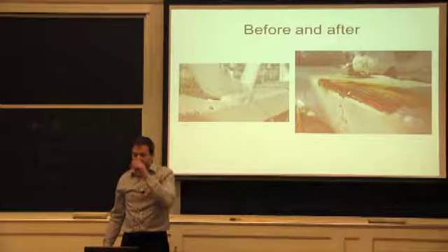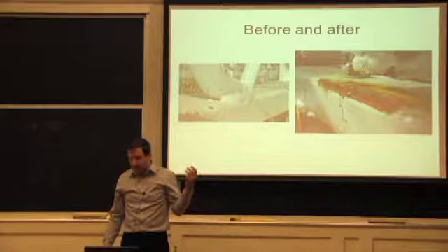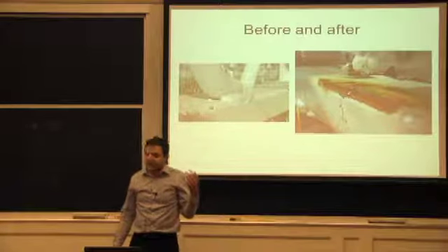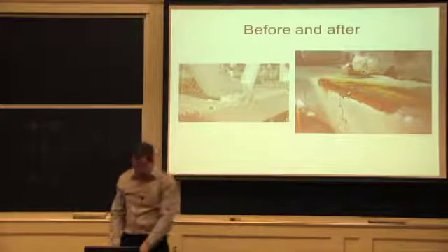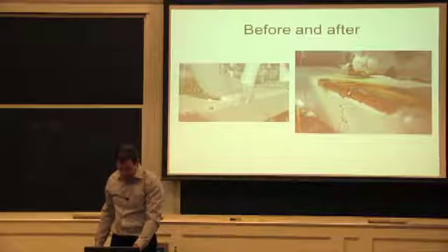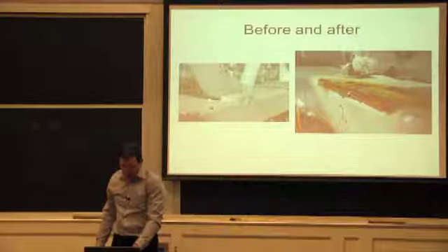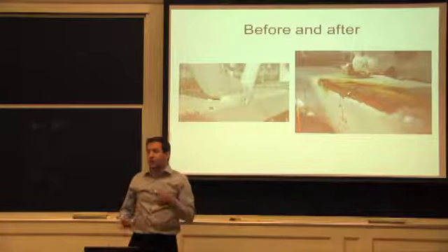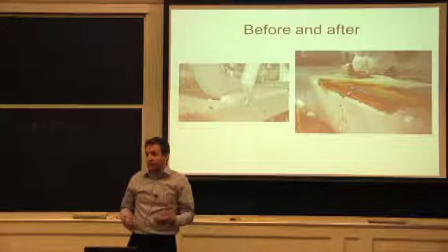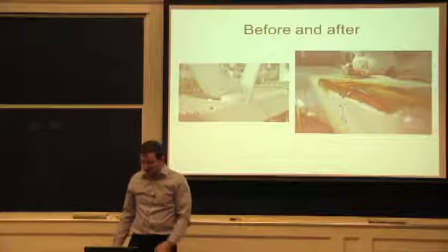And in the other class, I talked a lot about why that weld is difficult to do. But the bottom idea is you're looking at a very heavy section. That's the diagonal that's coming down. And it's got to be welded to this rectangular tube, but the tube is thin. So you're looking at very different thicknesses of metals to be welded in a tight spot.